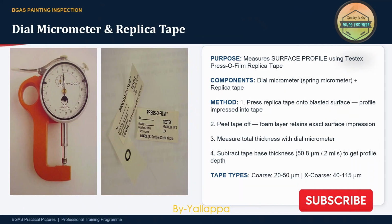This slide shows the Replica tape method. Replica tape captures the surface profile by compressing foam against the blasted steel surface. The compressed tape is then measured using a spring micrometer. The method is widely accepted internationally and provides reliable profile measurements. Always remember the examination formula. Measured value minus 50.8 micrometers equals actual profile depth.